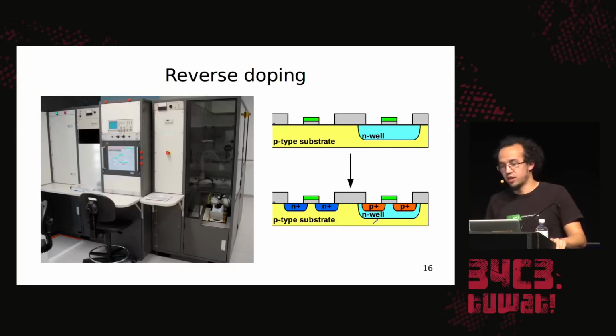And that's called a self-aligned process. So you don't need to align any photolithography step to your existing patterns. So this gives you much higher accuracy because you don't have any alignment errors. And well, this basically allows you to scale down your devices, which is obviously what you're going to do.